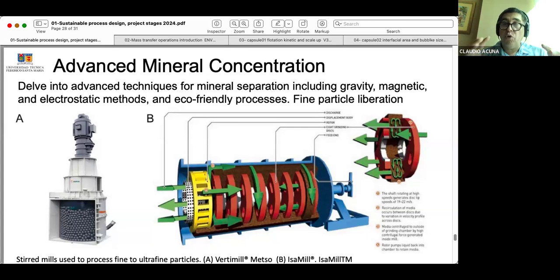When you have a bigger particle, there are more cracks, more probability of cracks, and then fracture occurs in the particle because of its mechanical strength. As you go to smaller particles, you have a more homogeneous material with no cracks, and then you are tearing apart the crystalline form. Understood the phenomenology?